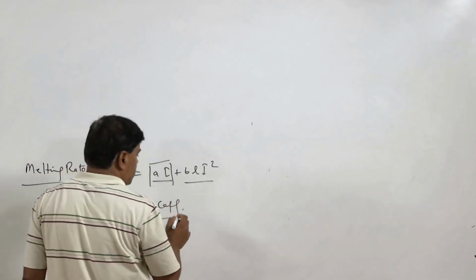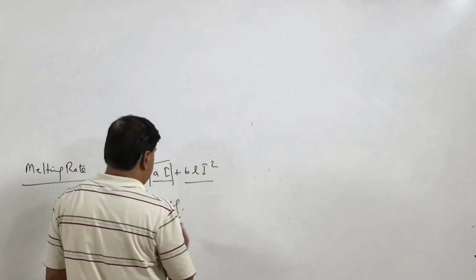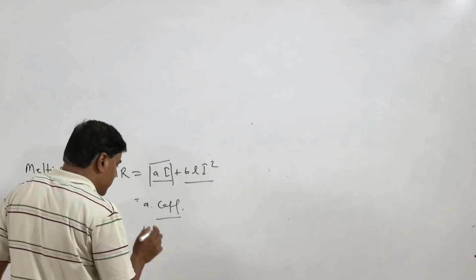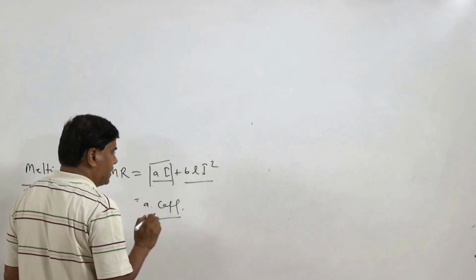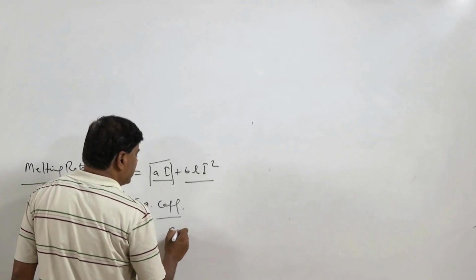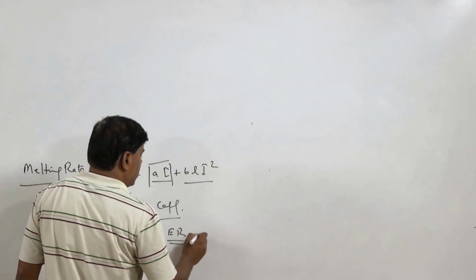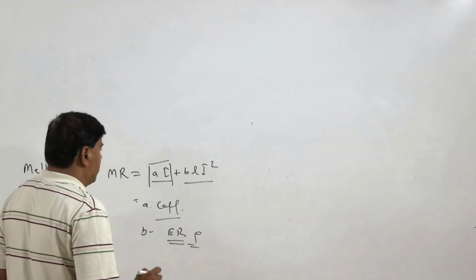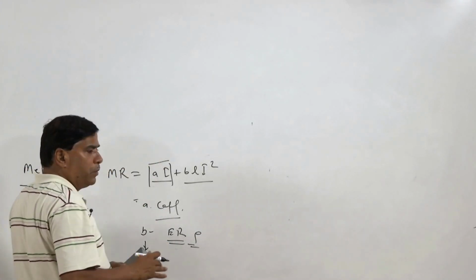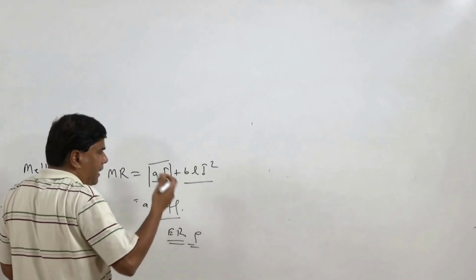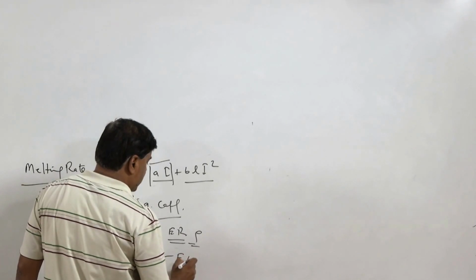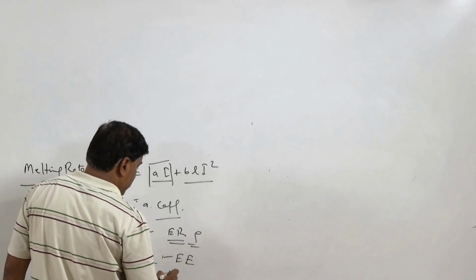I is of course the welding current in amperes, while B is the coefficient for material resistance related factors; the electrical resistivity of the metal is the big factor considered. High electrical conducting metals will have a low B value, while low electrical conducting metals will have a high B value. L is the electrode extension and I is the welding current.